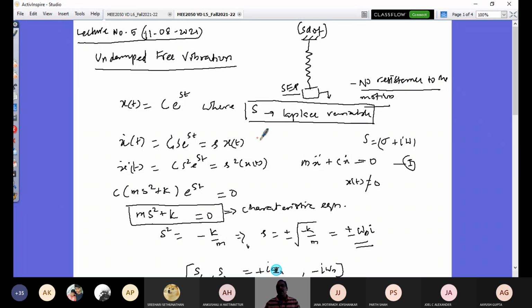You see here we have the spring and mass element alone, and you know what vibration energy means. At the static equilibrium position, the energy is 0 and it is a static condition. Then you give an initial velocity there, and you get a kinetic energy at the static equilibrium position. That makes this block move down, and then it comes back and goes up. When it comes back from its extreme amplitude position, it is because the kinetic energy imparted onto this mass at the start is getting stored as strain energy in the spring.